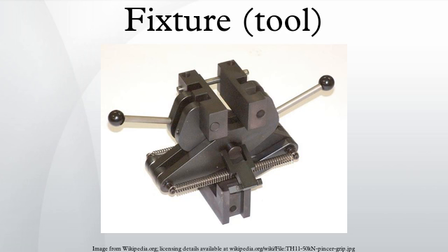Purpose: a fixture's primary purpose is to create a secure mounting point for a workpiece, allowing for support during operation and increased accuracy, precision, reliability, and interchangeability in the finished parts. It also serves to reduce working time by allowing quick setup, and by smoothing the transition from part to part. It frequently reduces the complexity of a process, allowing for unskilled workers to perform it and effectively transferring the skill of the tool maker to the unskilled worker.